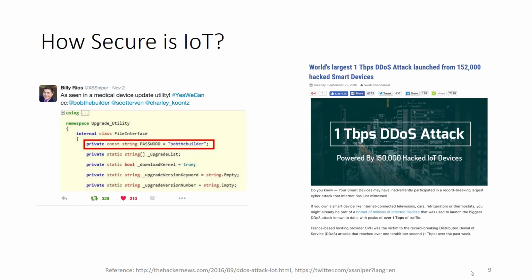So what can go wrong if you have a hard-coded password in your firmware? This particular firmware is used in similar kinds of devices and the family of devices. If you reverse engineer one device's firmware and get the password of one device, that means you got the password of each and every device of this kind manufactured by the same company.